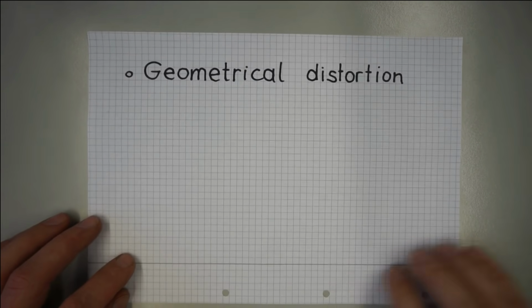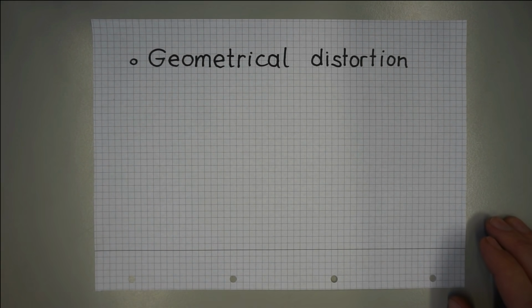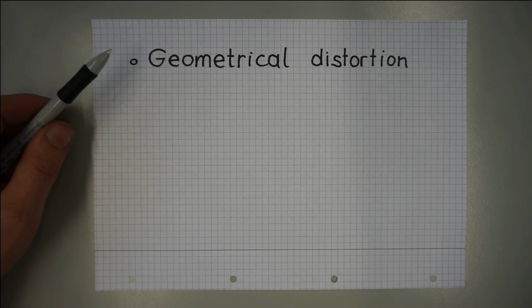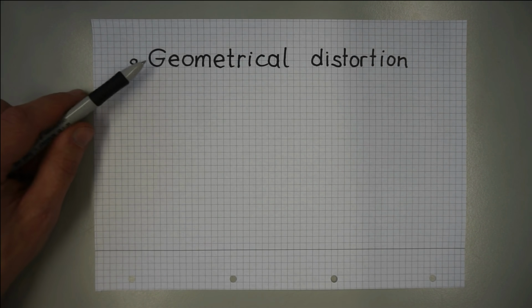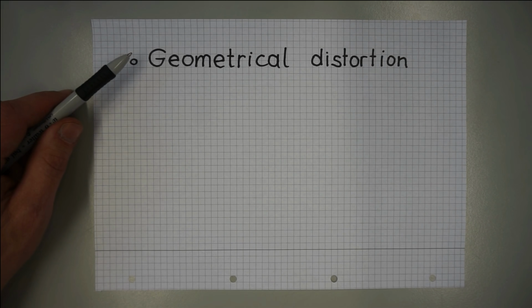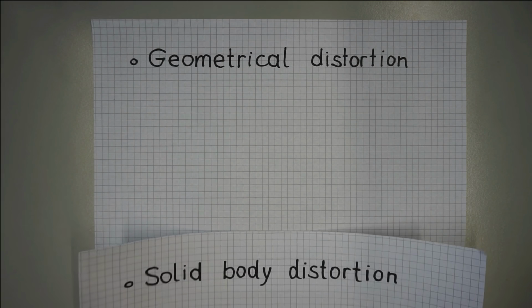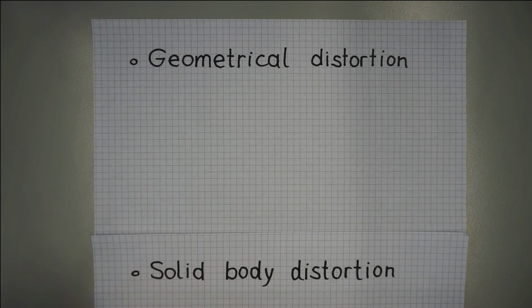As mentioned in the earlier episodes, welding distortion has more than just one cause. Let's first distinguish the two most relevant causes, and let's term the first one geometrical distortion. It is caused by opening or closing of gaps or by local workpiece buckling between tacks. I'd say that geometrical distortion messes with our workpieces mostly until we have properly finished tacking. From then on, I'd say the second most relevant cause, that is solid body distortion, takes the lead.